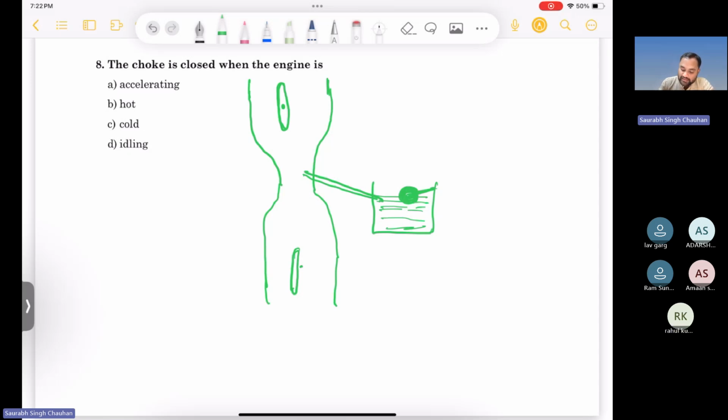So when the water goes down, this ball also comes down, and the opening that was closed now opens when the ball comes down. So water comes in and it starts filling. When the level reaches a certain level, this ball moves with the level and this passage gets closed. This is the basic mechanism. You can see some animation, then it will be more clear. Anyway, the basic purpose of this floating system is to maintain a level in this reservoir.